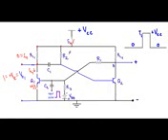Now you will see that this VCC is applied between this point to this point, and you will see that the R2 and the base emitter junction of the transistor Q2 is in series. That means the portion of voltage that is dropped across this base to emitter junction of the transistor Q2 will drive the base to emitter junction of the transistor Q2 in forward bias. Therefore now our transistor Q2 will be in on state.